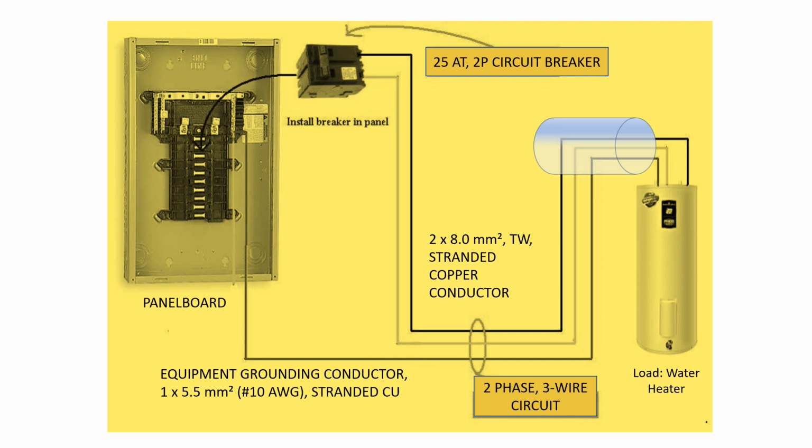And this is our conduit or raceway, which is 3/4 inch in diameter or 21 mm diameter, EMT conduit. If it is a PVC, the same procedure, you will go to the table and find a value or number of conductor which is more than 3 or exactly 3 because we have here 3-wire circuit.